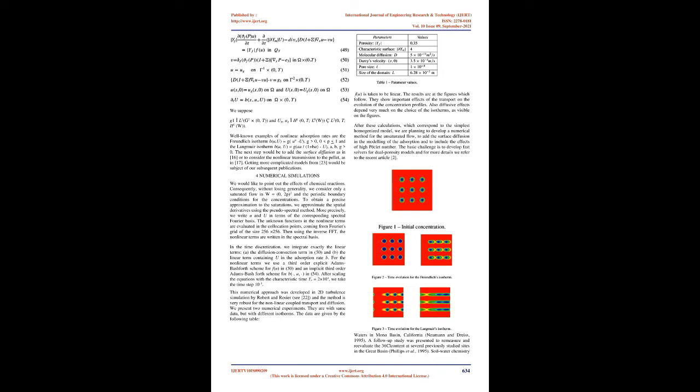First- and second-order reliability methods were applied as alternatives to Monte Carlo simulation in the probabilistic analysis of groundwater contaminant transport and remediation, Hamed et al., 1996. A 2D FE model was interfaced with a reliability analysis program that provided the probability that a contaminant exceeds a target level at a well. Covariances of velocity, head, and log hydraulic conductivity under quasi-steady flow were developed, and their effect on advective transport was examined, Zhang and Neuman, 1996a.